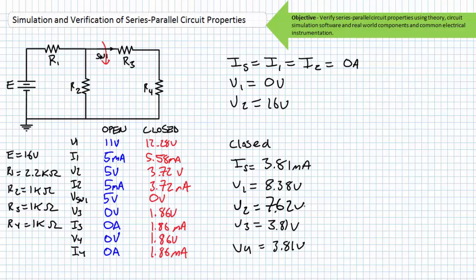Additionally, using a voltmeter referenced to ground, both terminals of R1 would be at 16 volts when switch 1 is in the open position, and there would be no differential across it. These observations made while switch 1 is open support the conclusion that R2 has been opened. Observations made while switch 1 is closed additionally support the same conclusion that R2 has been opened.